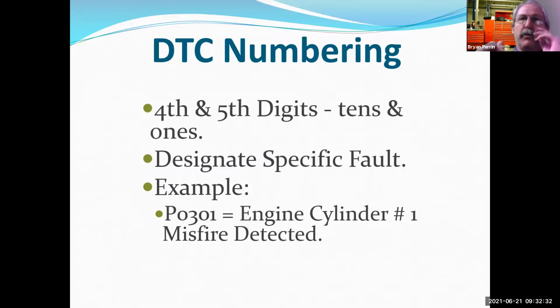I want to look at both of those things, because many times it is as simple as, oh, a 301 misfire, I go check, I've got a bad ignition coil or a bad spark plug or low compression or something. Yeah, there's something wrong with that cylinder. And that's going to fix the car probably on a misfire code 95% of the time, 98% of the time. But unless you can step back and ask the other questions, you're never going to fix that last couple of percent. And those are the cars where the code keeps coming back and I've replaced every part 3 times. Well, let's look at what's actually setting the code.